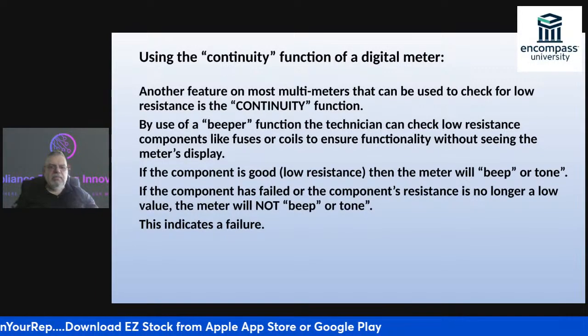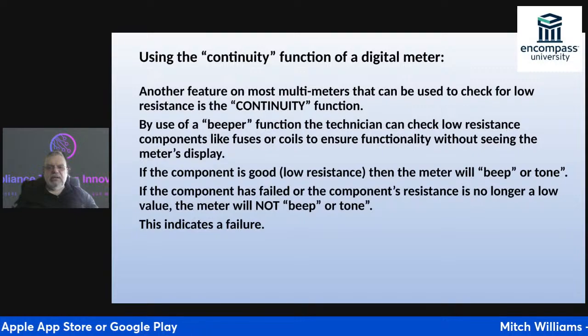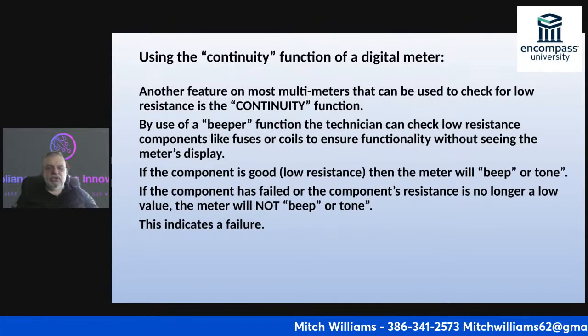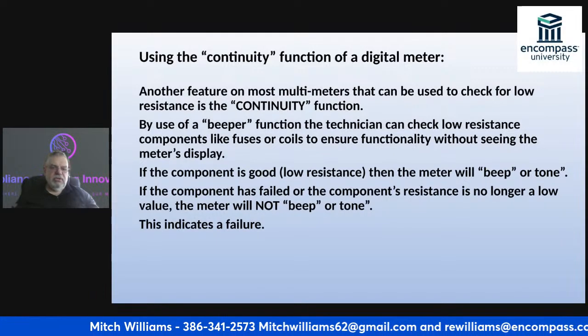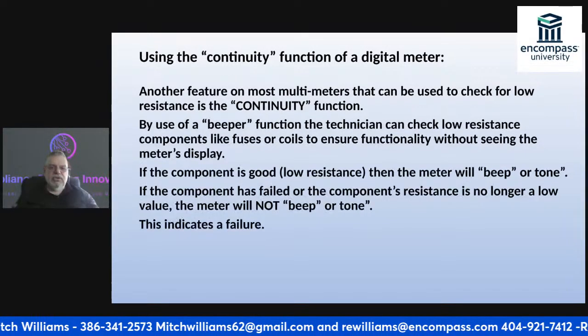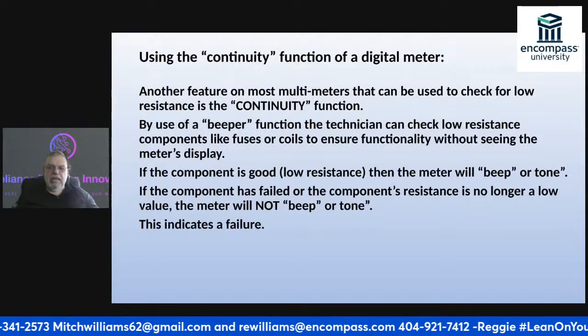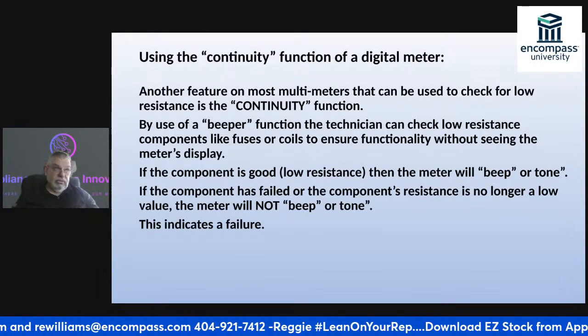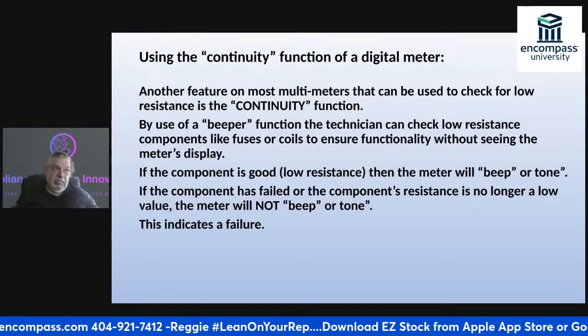By using the beeper function, the technician can check low resistance components like fuses or coils to ensure functionality without seeing the meter's display. If the component is good, low resistance, then the meter will beep or give a tone. Mine has a tone. So mine didn't just beep, mine had a tone.